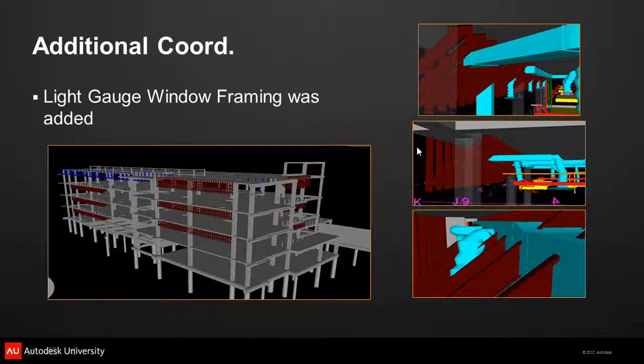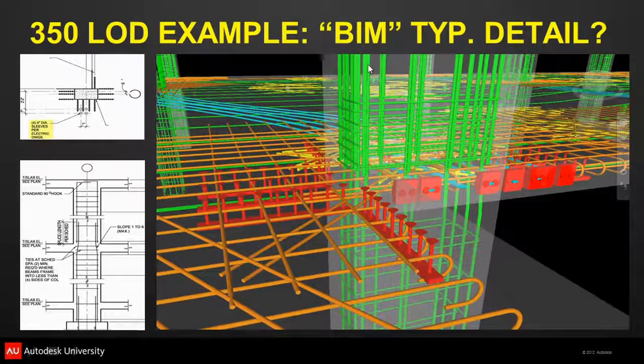To do any kind of plumbing coordination, you need a good structural model that includes this trade information. So these are cold form metal studs. In design, the structural engineer provides a specification. However, to do that cross-trade coordination, you need things like these kickers modeled, and they're not available at design level. This is a project where the risers need to be defined, and the design level model didn't show that. It just showed the stud rails.